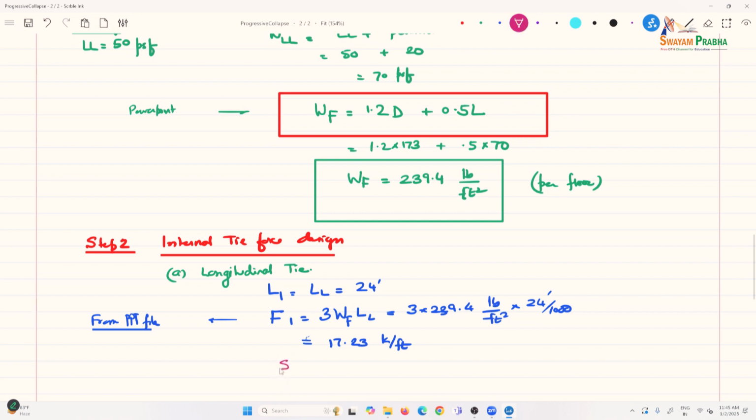And so, the steel area required, this is additional steel, goes on F equals As Fy, assuming the steel yields at that force, which in catenary action it will, multiplied by the overstrength factor. The 1.25 accounts for overstrength in steel or overstrength in concrete. We had talked about that earlier on.